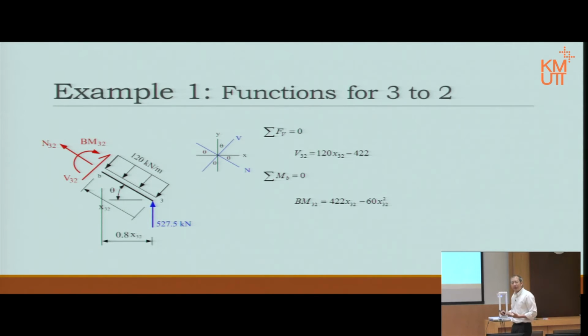Now we have all equations, so we're going to start drawing the graph. And again, differentiate bending moment. This time, notice though, differentiating bending moment we get minus shear, because our x goes against the proof from last time. Let's continue. But it still means that our bending moment will still peak at shear equal to 0, because minus 0 equals 0. Doesn't matter, it still peaks at the same place. So we still can use that concept.